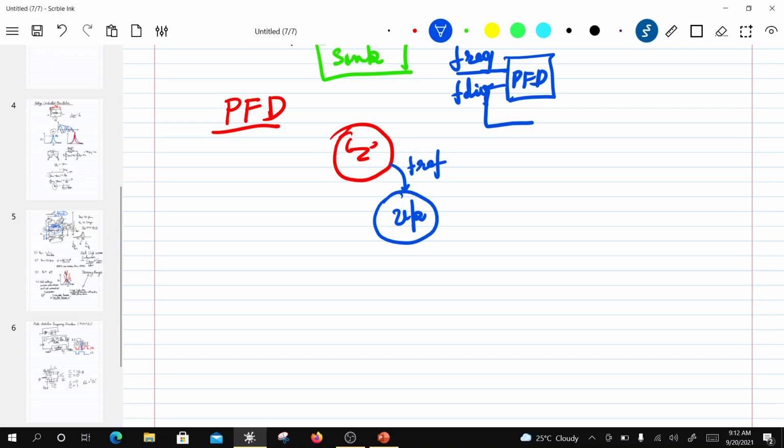Okay, so if FREF comes first, and then FDIV comes, it is going to be in this state. So let's undo that. Okay, so this is going to be the state, where the output node voltage of the loop filter is going to be pulled up, right?